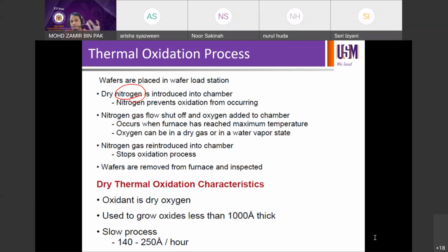So it's oxide yang formed by ambient process. You tinggal je, you measure. After 2 days, you will see some thickness of oxide. And we call that as native oxide. And the typical native oxide is around 3 to 5 nano. Okay, depending on the temperature, humidity, the duration that you left the silicon wafers on the bench exposed, typically in the region of 3 nanometer to 5 nanometer.